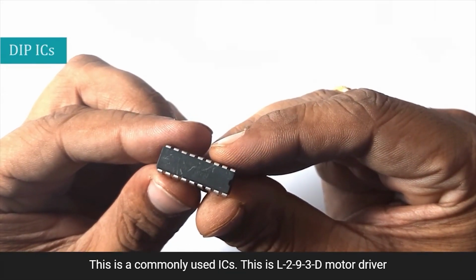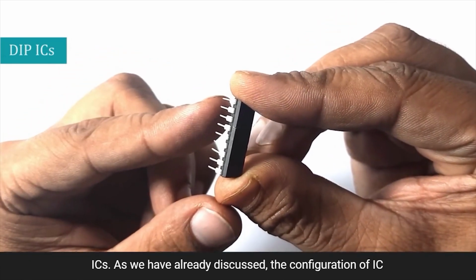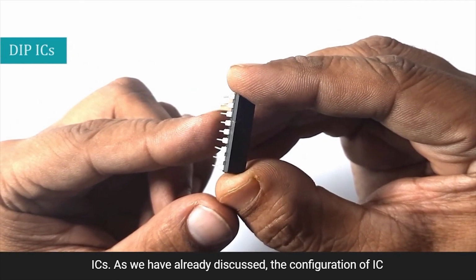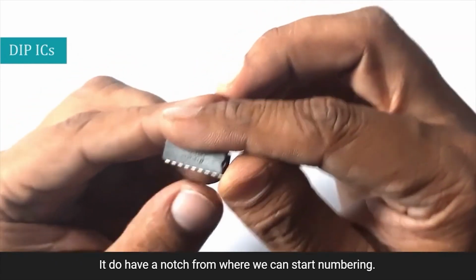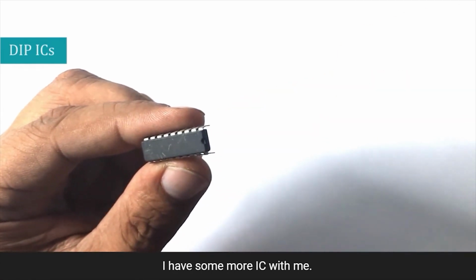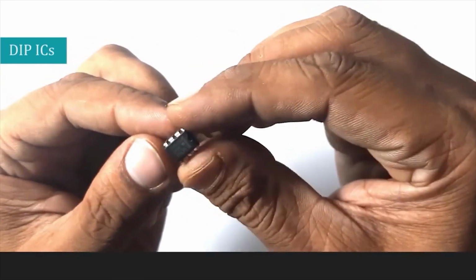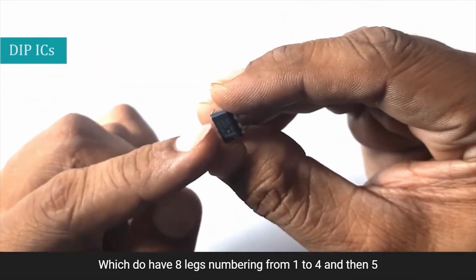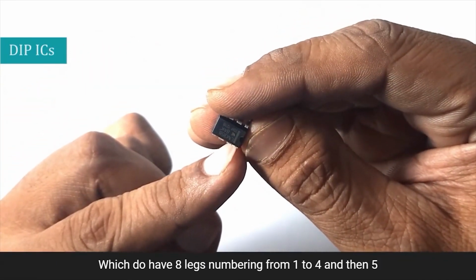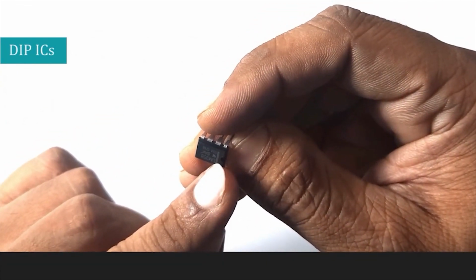This is a commonly used IC. This is the L293D motor driver IC. As we have already discussed the configuration of an IC, this IC has a notch from where we can start the numbering. I have some more ICs with me. This is an 8-pin DIP IC which has 8 legs, numbered from 1 to 4 and then 5 to 8, starting the counting from the notch.